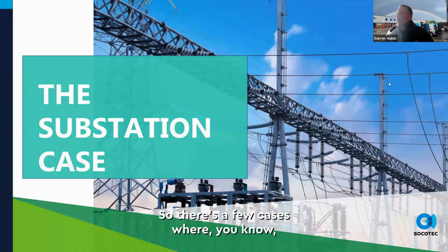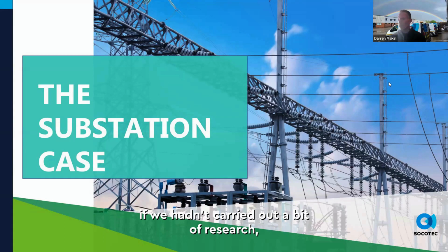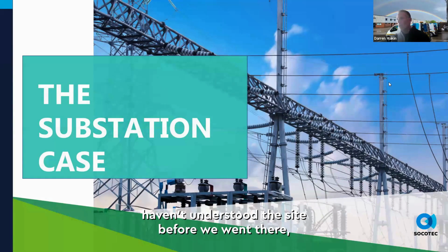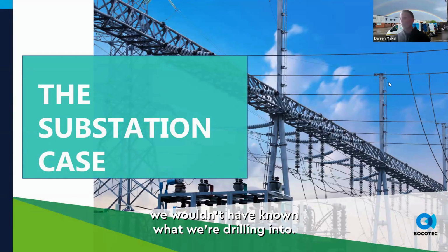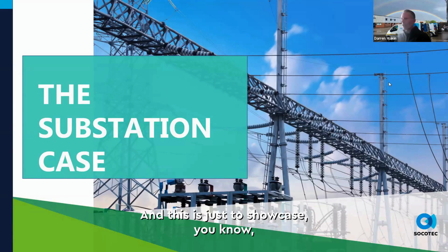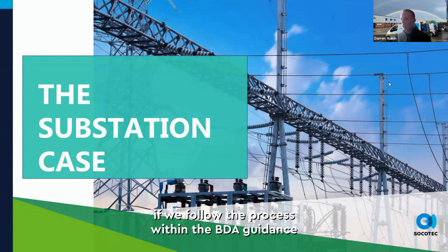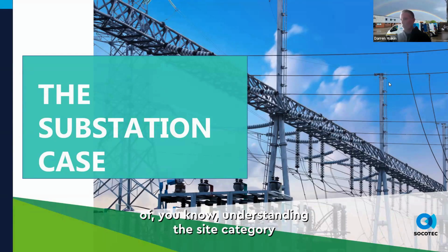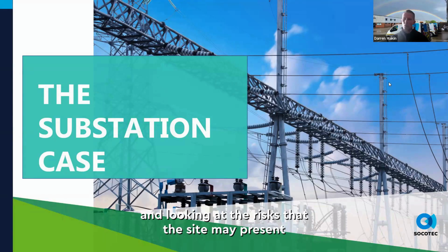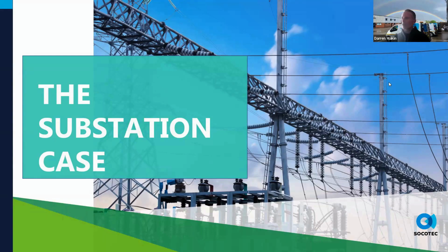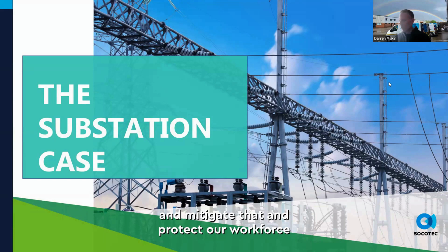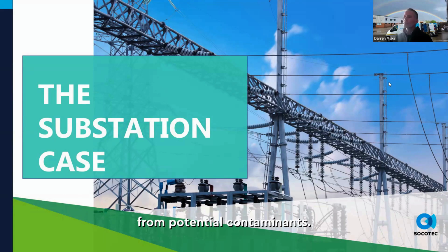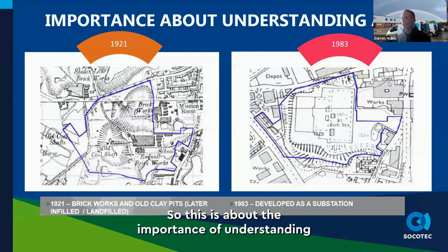So there are a few cases where, if we hadn't carried out a bit of research and hadn't understood the site before we went there, if we didn't have the desk study information or the pre-construction information, we wouldn't have known what we were drilling into. This is just to showcase that if we follow the process within the BDA guidance, understanding the site category and looking at the risks the site may present prior to mobilization, we have a good idea of what may be in the ground, can mitigate that, and protect our workforce from potential contaminants. So this is about the importance of understanding the site.